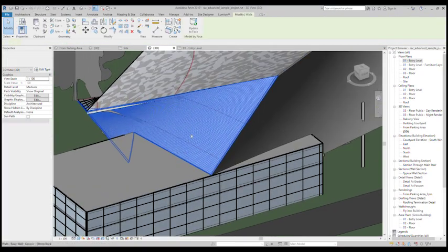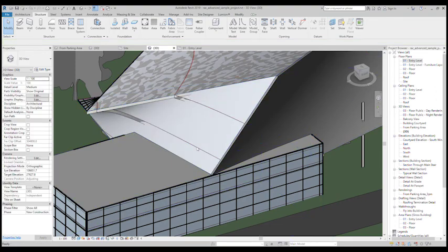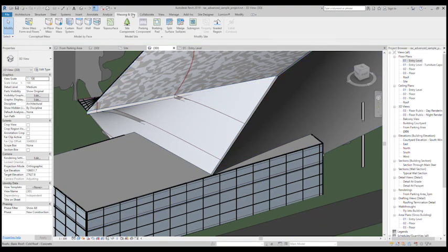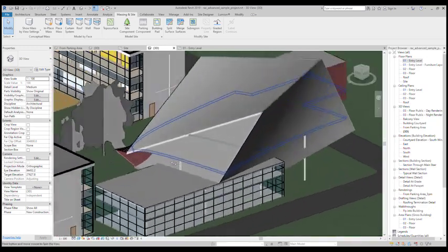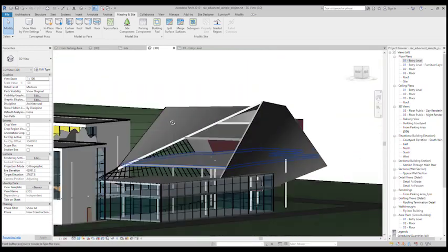Let me hide that, delete that wall. And for now, as we're working with columns, I'm going to hide my masses. I do that by clicking on massing and site and saying show mass by view settings. If the view settings are hiding masses, then the masses will be hidden.